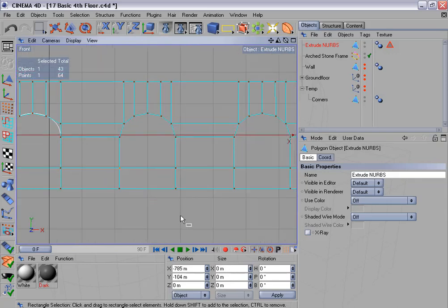So over here, select another reference point, copy the X position, select this entire row, paste the X position and align the points. Okay, then select this one, copy the X position, select this point, paste it, and I'm going to do the same thing here and here. And here let's select this one as a reference point, copy the X position, select the entire row, paste the X position and align these points.